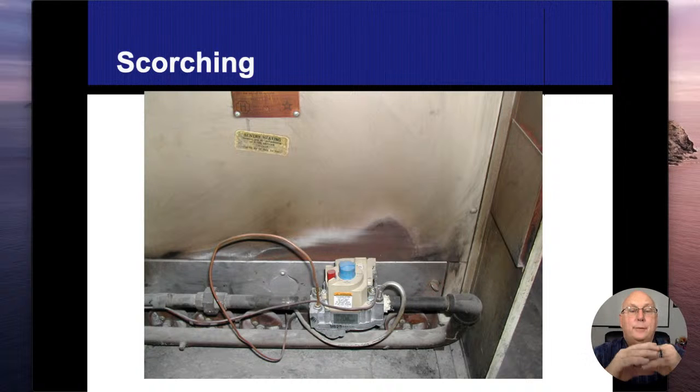And if it's coming out of there too rich, maybe a pipe is broken and it's not drawing in enough oxygen to ignite right away. So it pushes the gas and then the gas starts spilling out of that opening. It's going to eventually ignite, and when it ignites, it does create a flash that comes in there, and that flash is what ends up leaving the scorching marks. Sometimes we'll see rust marks on there as well.